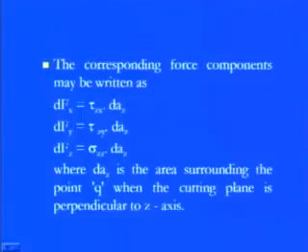Means that now we have two shear stress components in x and y, because as I told you, the tau zx, because we are working in the z domain, which is exactly this, like you see here, the inclined plane towards this. So this is my z plane, and here this is my sigma z, or we can say Fz. So I have sigma zz, meaning both the domain as well as the force direction are the same. That's what you see, the normal stress component is there in the z direction, while the shear stress components are there in the other two directions, because we have the same domain and two different directions of the forces, like x and y.